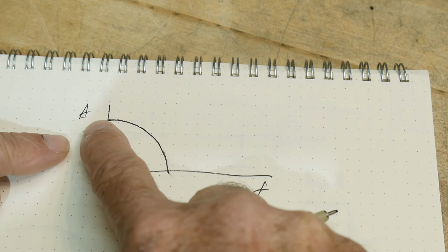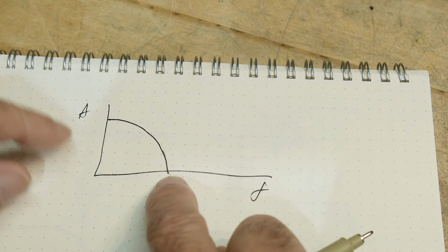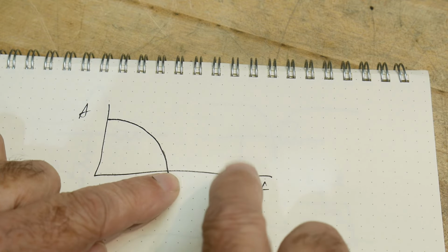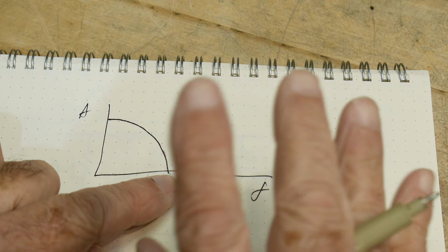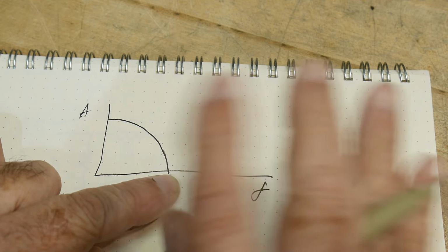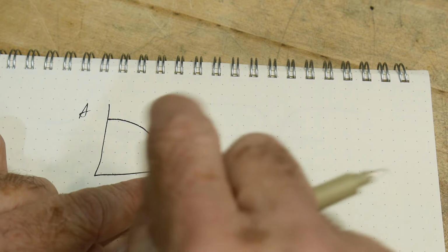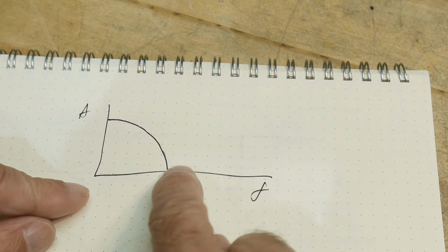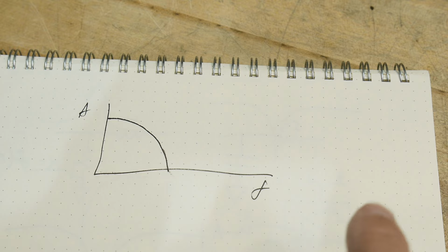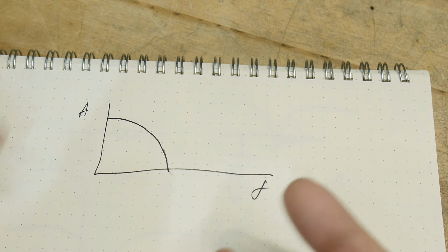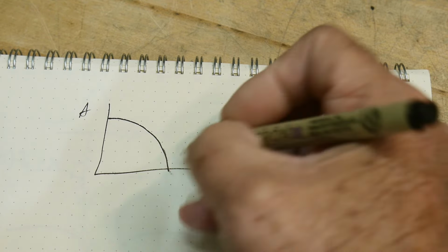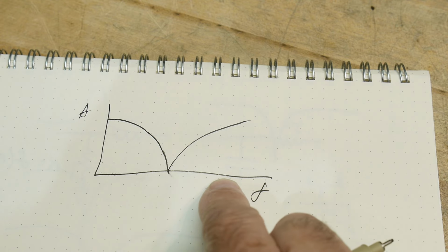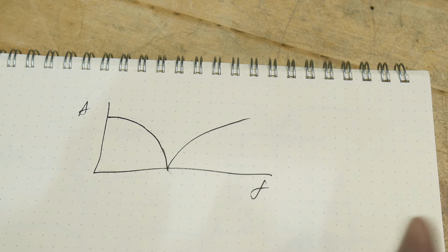That if your capacitor is able to kill 1 megahertz, it will certainly kill 10 megahertz and 100 megahertz. You know, capacitors will conduct higher frequencies. And so you're kind of taught that this thing goes down and then just stays down. But we've just seen that the inherent inductance that's also part of the capacitor will make it do this. And now, these frequencies out here that you hope that you're killing are no longer killed. They go right through the system.